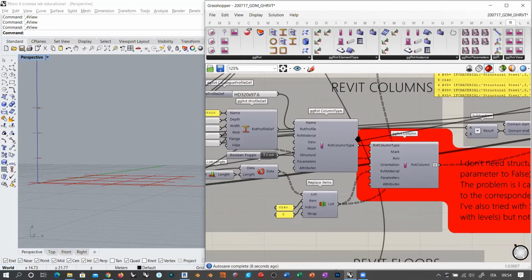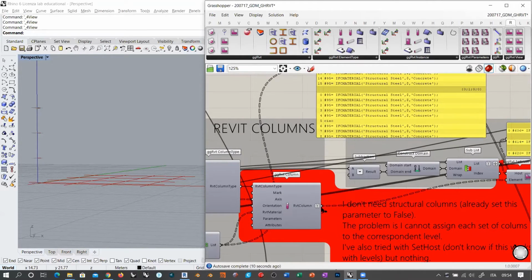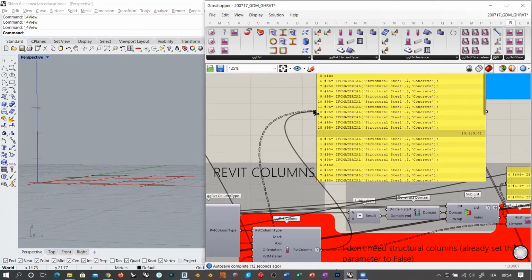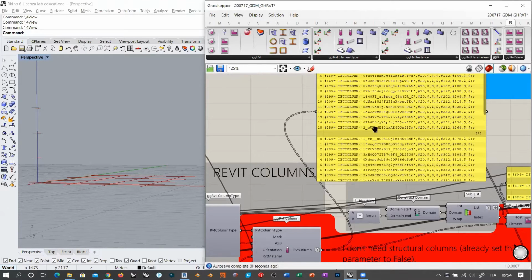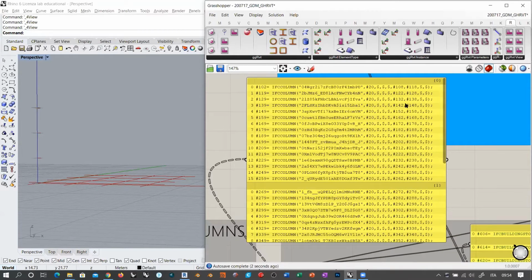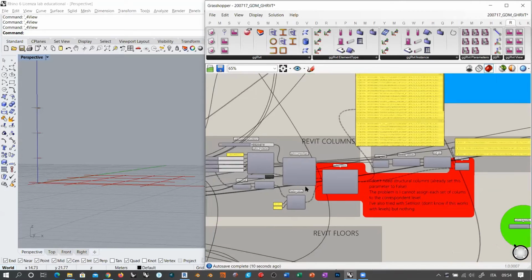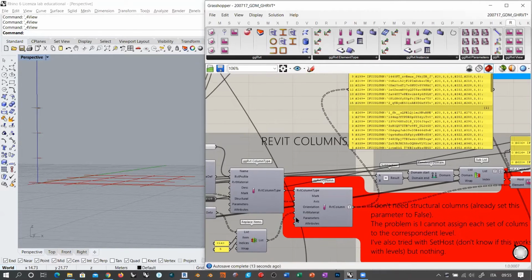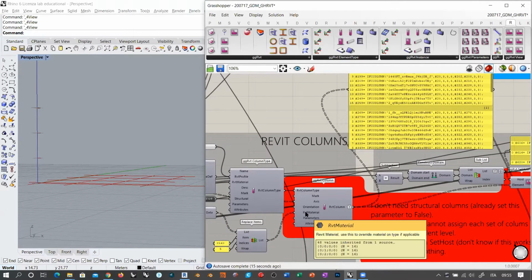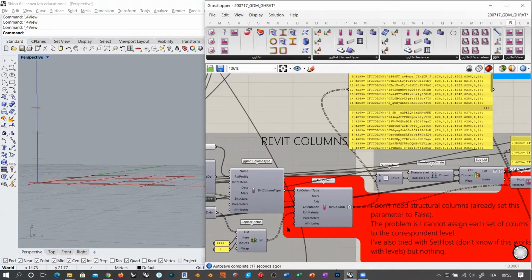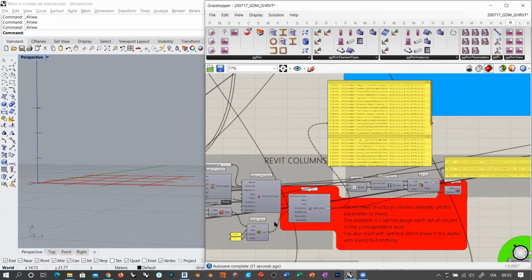Okay, so the thing with instances is that not all the parameters are visible inside the instance, because they are basically a set of strings or symbols that tell Revit how this instance is going to work. But nevertheless, remember that if you do this, you are substituting the material for some of the columns, corresponding to these indices here. This might be useful.